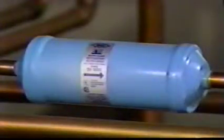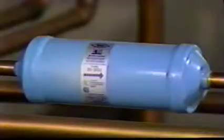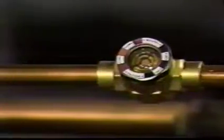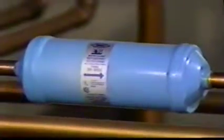In the liquid line, the situation is slightly different. Liquid line filter dryers are often replaced, but not because of pressure drop. It is usually because there is still water in the system, and the liquid line filter dryer can absorb no more. To remove the excessive moisture, a new dryer must be installed.